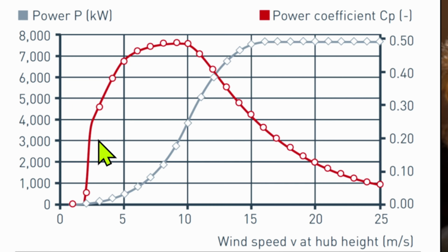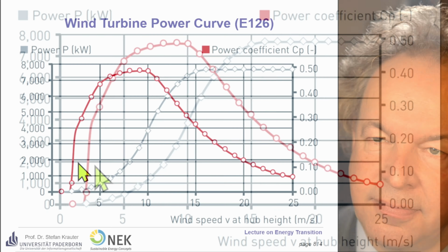And you have here the power coefficient, or in other words, the conversion efficiency. The maximum is reached here in the vicinity of 10 meters per second of wind speed, and is close to 50% conversion efficiency. If you reach the saturation, the conversion efficiency is strictly going down.